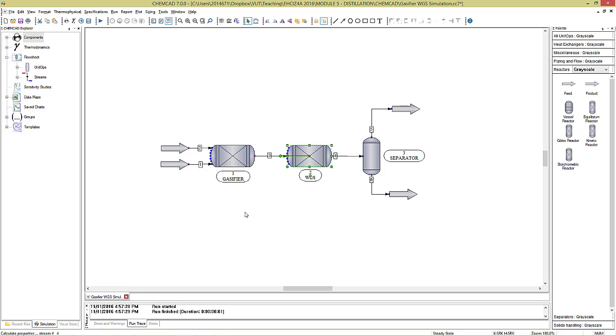This one, I'm just guiding you through the flow sheet synthesis. For your flow sheet, you need to specify everything. If the pressure needs to increase, I need to see a compressor. If the pressure needs to reduce, I need to see an expander, a valve. If you're feeding steam, I need to see where the steam comes from. Usually you are given water, steam is not available on site. I need to see you boiling the water to form steam that you're going to feed into your system. If you have a distillation column, I need to know what you're going to heat the bottoms with. I need to know what you're going to cool the condenser with. So all those need to show in your final flow sheet. I need to see the process streams. I need to see the utilities as well.